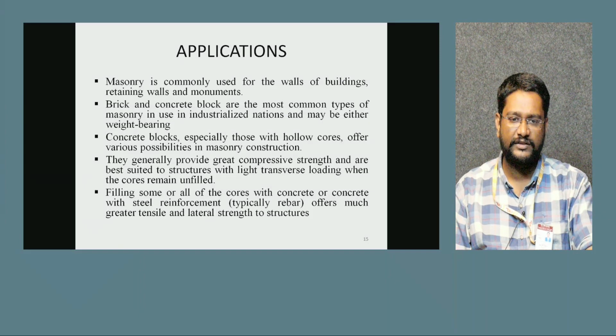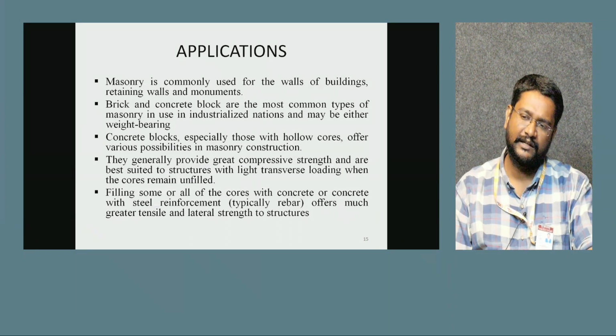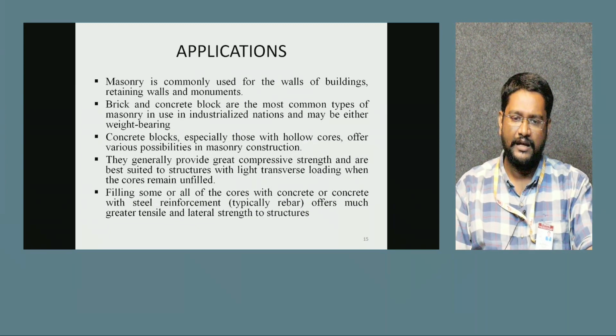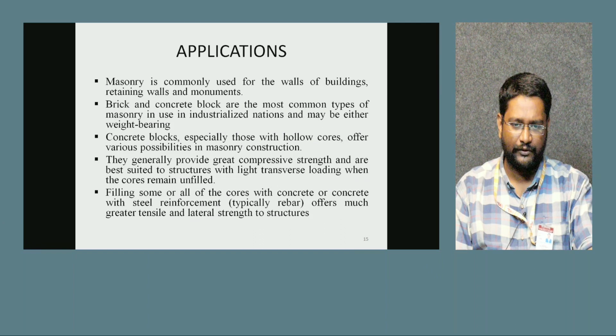Concrete blocks, especially those with hollow cores, offer various possibilities in masonry construction. They generally provide great compression strength and are best suited to structures with light transferring loads when the core remains unfilled. For example, take hollow blocks: the hollow block has material only at the periphery, and the inside is vacant.